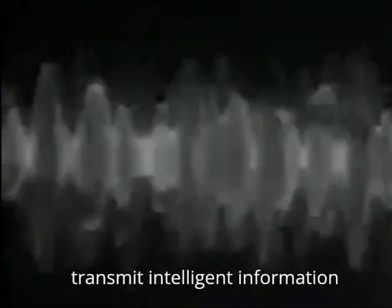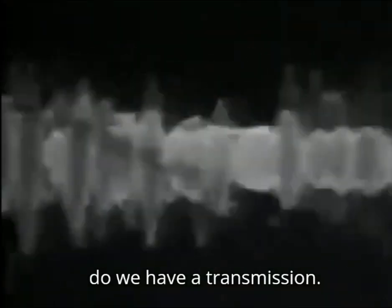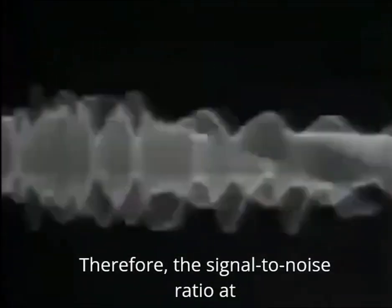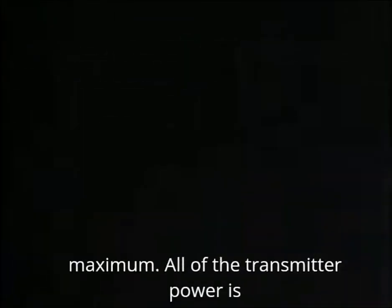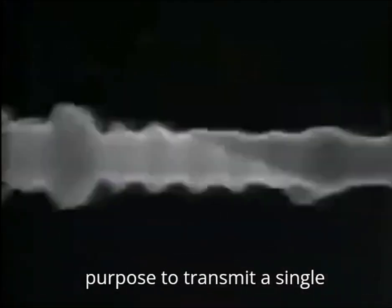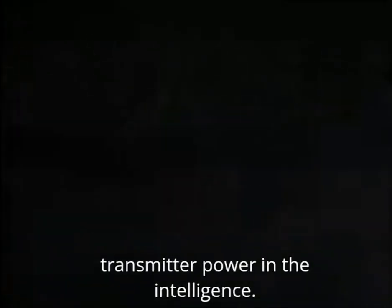Only when we transmit intelligent information do we have a transmission. All of the power of the transmitter is directed to the intelligence. The bandwidth is much less. Therefore, the signal-to-noise ratio at the received end is higher. And of course, our transmitter efficiency is maximum. All of the transmitter power is delivered to the intelligence. This, then, is the big difference between single sideband and ordinary amplitude modulation. We have accomplished our purpose to transmit a single sideband signal, all of the transmitter power in the intelligence.